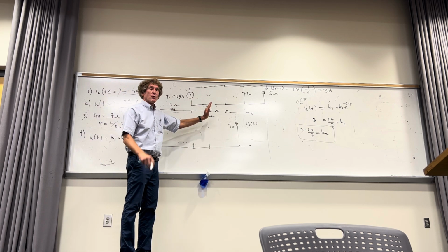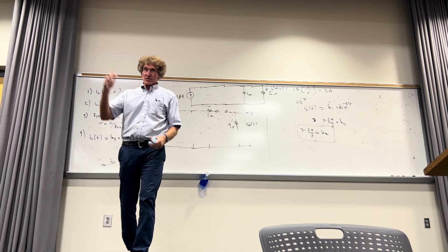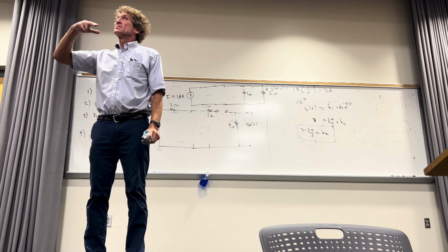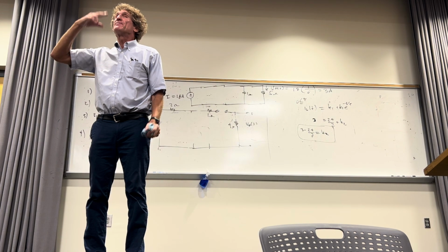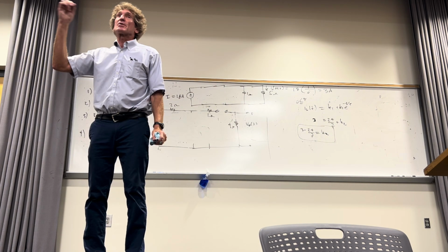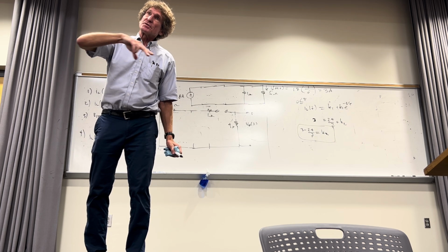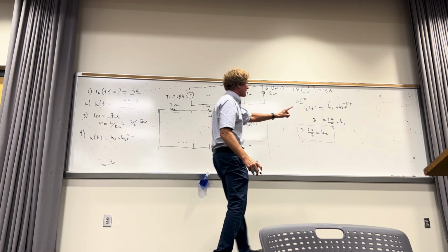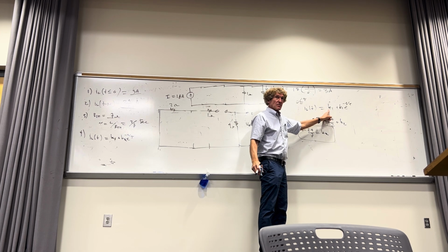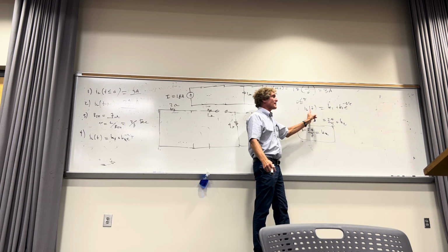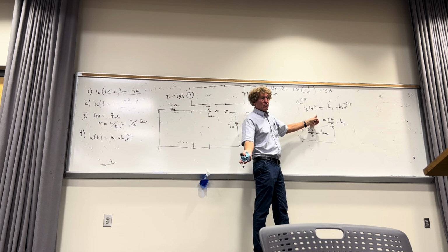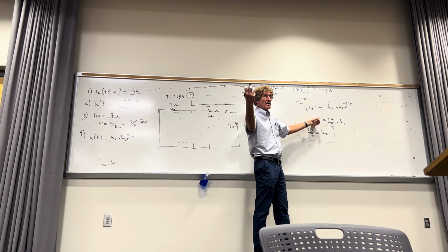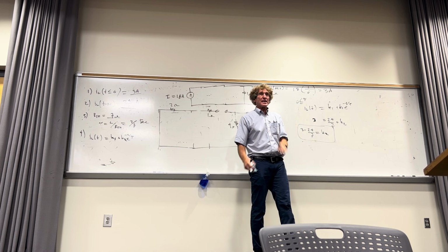Now, this is a very important point. When the switch transitions from t less than 0 to t greater than 0, that current doesn't instantaneously change. It can't, because it would imply an infinite voltage. The current before is the current after. So after the switch closes, and now we're using this equation, we get K1 by looking at infinity. Got me? That's the current at infinity, but to get K2, we have to put the current here at t equals 0. That's the current less than t equals 0, which is the current just as the switch transitions. You with me on that one? So you put that here, so that would be K2. Do you agree with that?